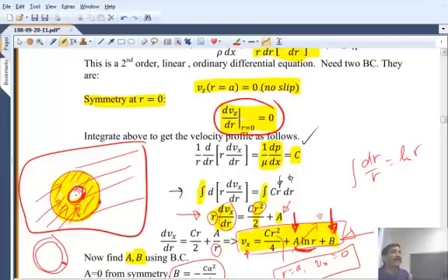It still is not a fully answered, resolved question, but we understand where it occurs, and that has to do with stability. What do I mean by stability? Since we digress, maybe we should talk a little bit about it. A very common experience, I don't know how many of you are smokers, but if you're not a smoker, if you have incense or whatever, you light an incense or a cigarette, and let the smoke evolve from there, and observe what happens to the smoke. It'll go as a laminar, very uniform steady stream, and then it just breaks up. That is what we would call a laminar to turbulent transition.